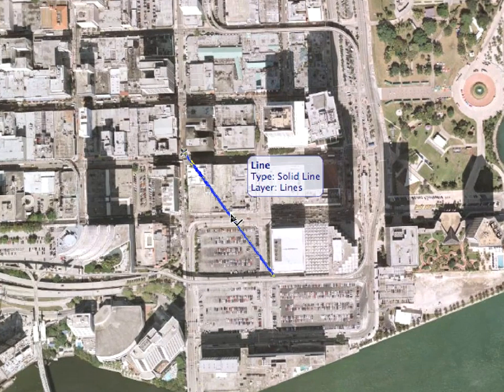Going back to ArchiCAD, we drew a line over the placed image of the downtown area between the same 2 points on the map image. We zoomed in as close as was sensible to make it as accurate as possible. We selected both the line and the placed drawing of the image, and using the Resize command, we resized them both graphically. The graphical resize operation's origin was one end of the line, and it was done in such a way that as a result, the line measured 237,559 millimeters, just as in Google Earth. With this, we achieved that the image was enlarged to the correct size.